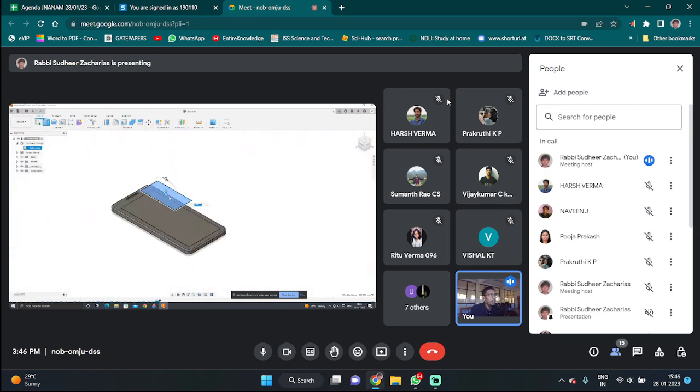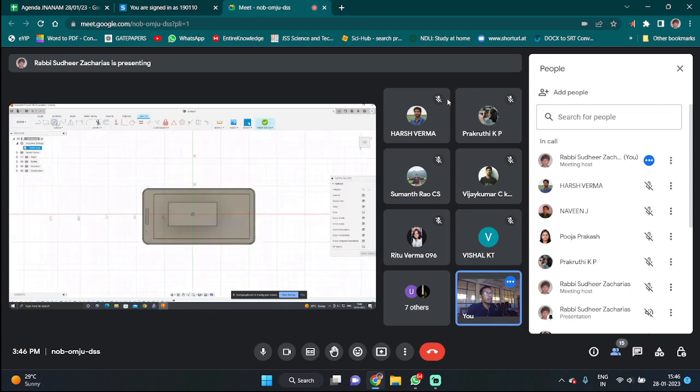So now whatever diagram or whatever model you are doing, it has been created on the plane which you have defined. So this also might be another useful option, because whenever you want to stack different objects, you don't want it to mess up the existing block, right? So you can define your own plane by the construct or offset plane option. You can select an existing plane, and then wherever you want to create, you can just move that, enter. Now you can create another sketch there.